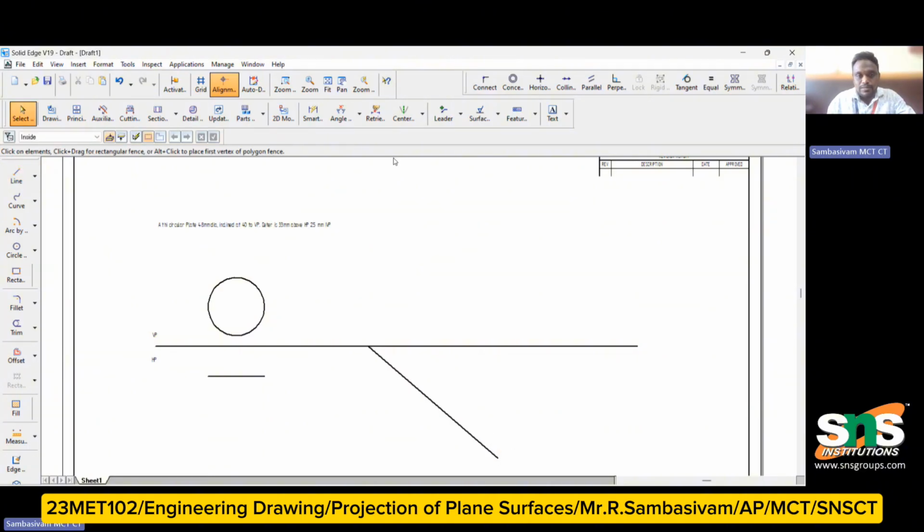So to understand whether the angle is right or not, I have to check that the difference between them is 40 degrees, right? So now I am making this one. So the total length is 48 mm right now. This 48 mm line I have to draw from this sector. So the length is 48 mm right now. So I have drawn the 48 mm line. For clear understanding, I am going to change this to red color. So the projection line will be there.